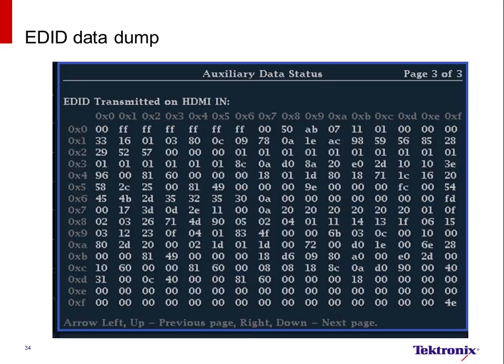On the WFM 5250, we can also look at the EDID that we send to the transmitter. The EDID is a 256 byte hex dump. There is a parsing table provided with the device if you need to turn around and parse out what the data actually states that is being sent to the transmitter.